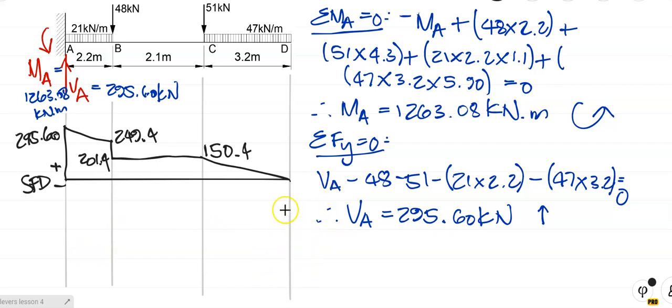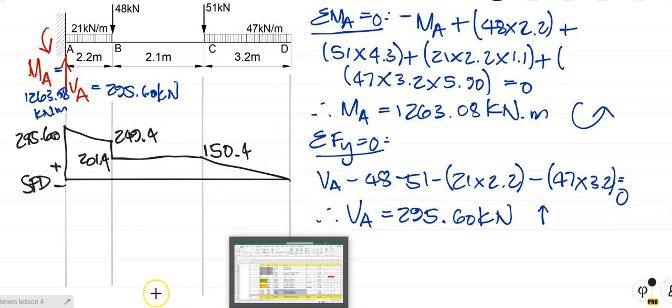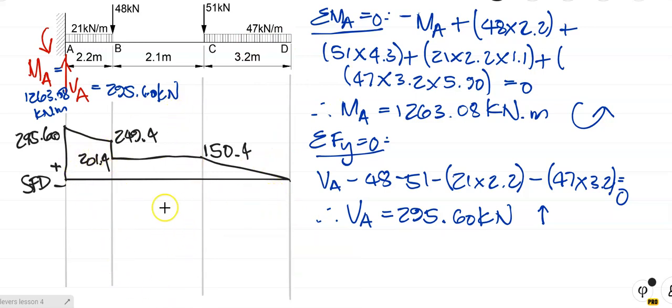Right. Now, if you look at the previous shear force diagrams, they crossed, they went up and down, but what do we see for a cantilever? The shear force diagram is above the zero line all along the way. So the area there is positive throughout. The whole area is positive. So there we have a trapezium. Between B and C we've got a rectangle, and from C to D we've got a triangle. I'll say that again: notice we've got a positive area all the way through above the zero line for a cantilever.